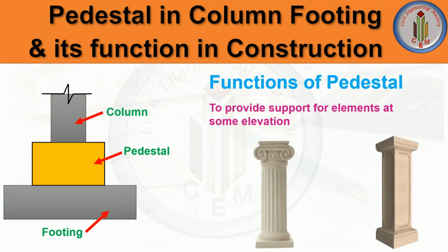In that case, we don't need to design the pedestal as a vertical compression member. It is only provided for the aesthetic purpose. So in some elevation, we can also provide pedestal like this. So this is not a load carrying element now. It is only provided for the aesthetic purpose.